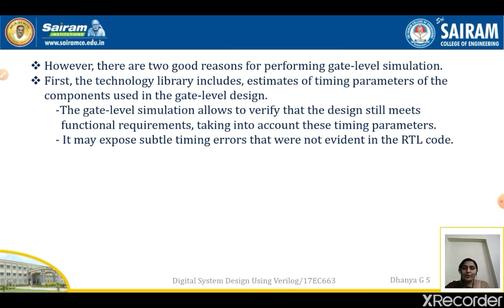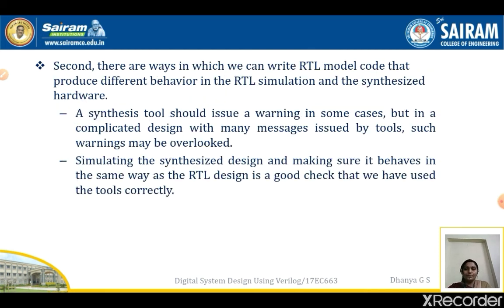However, there are two good reasons for performing gate level simulation. First, the technology library includes estimates of timing parameters of the components used in the gate level design. The gate level design allows us to verify that the design still meets functional requirements taking into account these timing parameters. It may expose subtle timing errors that were not evident in the RTL code.